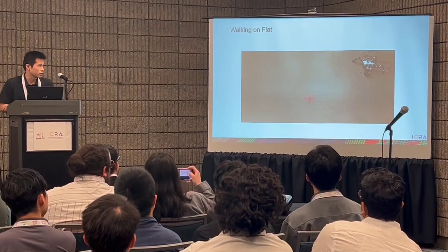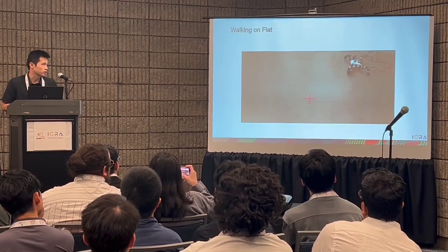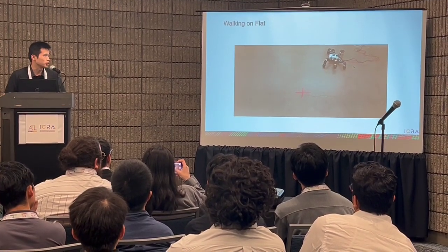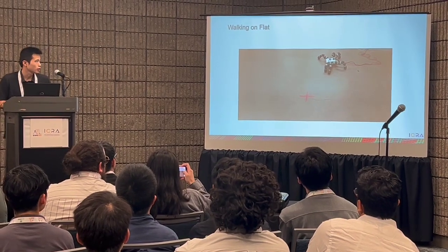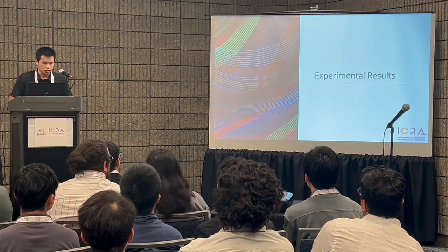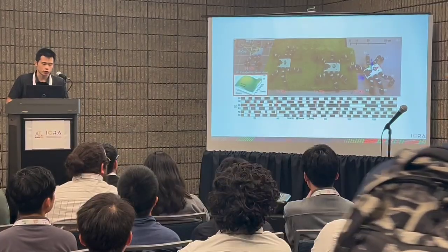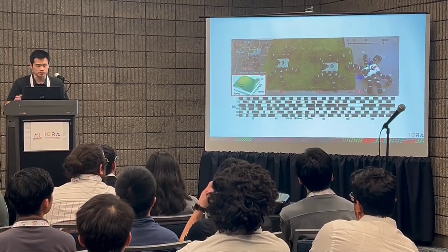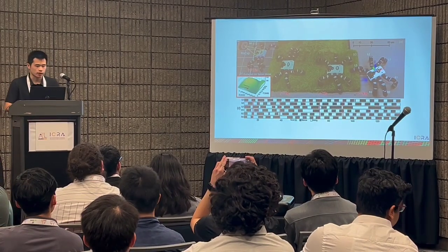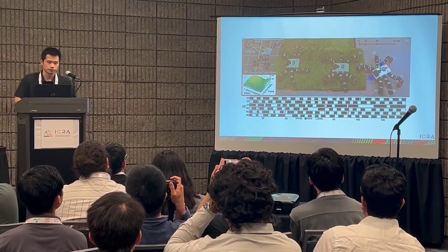And with this control architecture, we're able to achieve 6-legged locomotion on flat ground, and here it self-emerges into a tripod gait. For our experiments, we set up a motion capture system that tracks the robot torso's odometry data. We also track the swing and stance phase data from each leg of the robot.